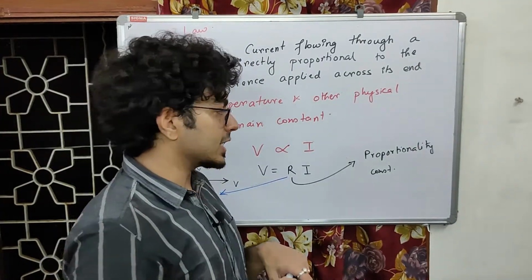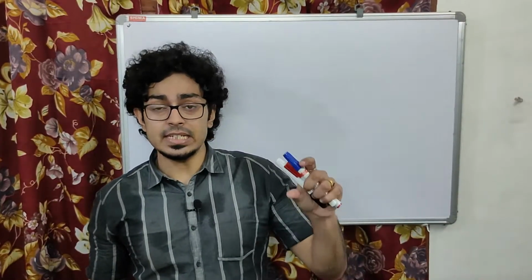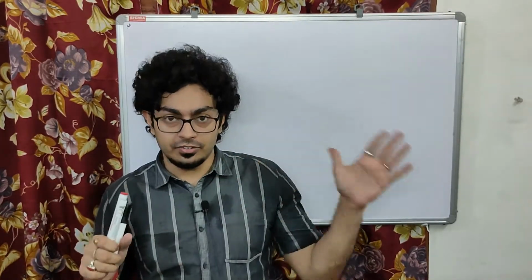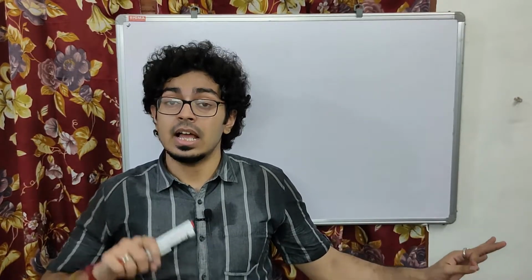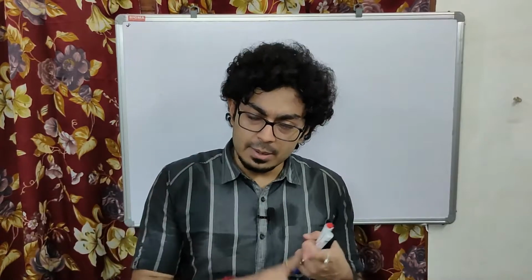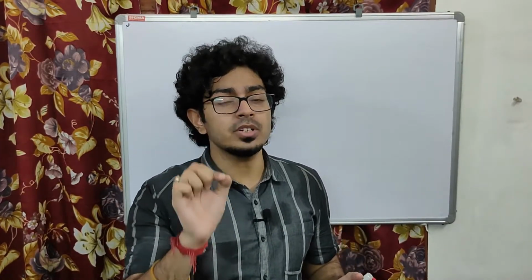Thank you. Next we are going to understand what is resistance and resistivity of any conductor or any material. It is found that different conductors, that is different materials of the same dimension, offer different resistance to the circuit. Suppose you take a 5 meter long silver wire of whatever cross-sectional area, and a 5 meter long wire of another material of the same cross-sectional area. You are going to observe that these two conductors give different resistance to the circuit. Same dimension, same cross-sectional area, still they are offering different resistance. So which property determines which material will have more resistance compared to another? From here we need to understand what this property is which separates one material from another, and makes a difference between the resistance of the conductors.